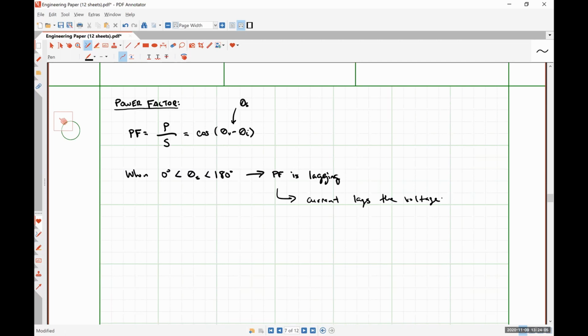Whenever we had the voltage drop over the inductor and the current flowing through the inductor, we saw that regardless of what we changed the frequency to, the current lagged the voltage by exactly 90 degrees. Well, for a non-purely inductive load, we're going to allow that angle to effectively just be positive, and it will still count as lagging, which means it has some inductive contribution.